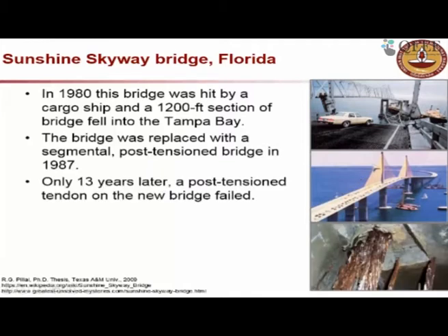However, about 13 years after the construction of this bridge, we found that the steel tendons inside these pillars were corroding very heavily. In just 13 years, you can see in the third picture on this slide, it's completely corroded. It's not at all acceptable for a bridge of this nature. Failure or corrosion at this level in 13 years is not really acceptable. So we have to design our concrete structures so that these kinds of things do not happen.